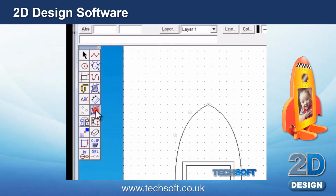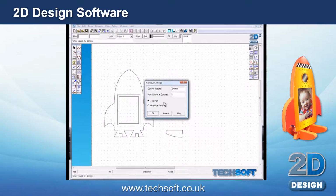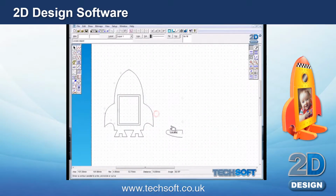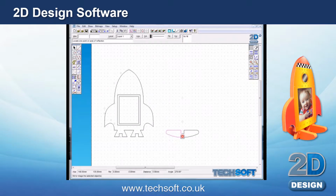Again we're going to use the contour tools, and this one's parallel to a line, 2.4, so it's the same as before, and OK, just on the inside. Make another line. And we're going to delete the bits we don't need again. You notice that's half of the stand. So we're just going to select, mirror the same as we did before, making sure repeat is selected. And that mirrors the stand.